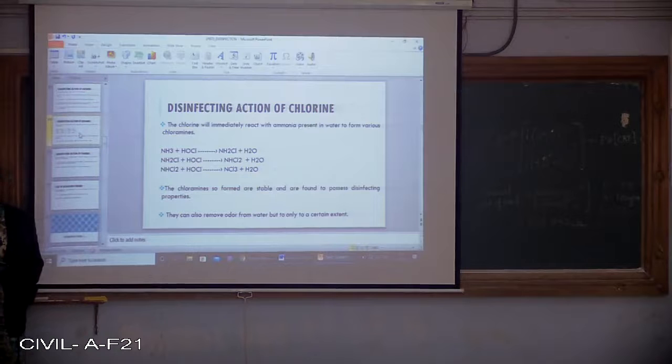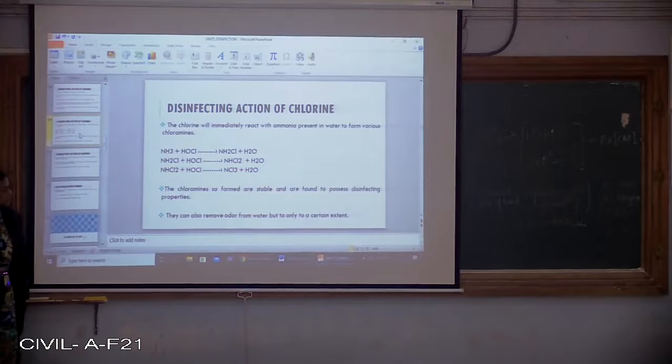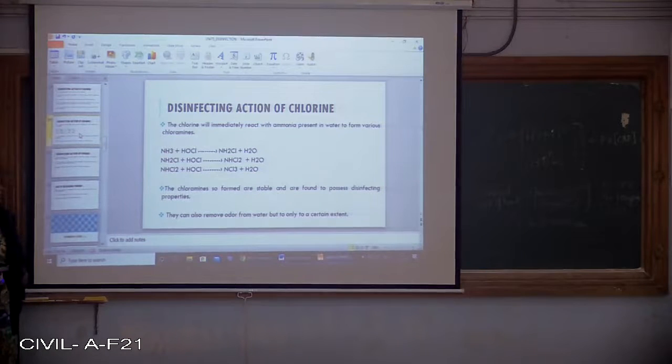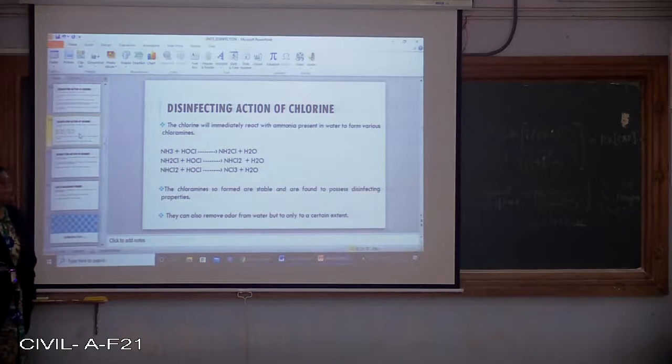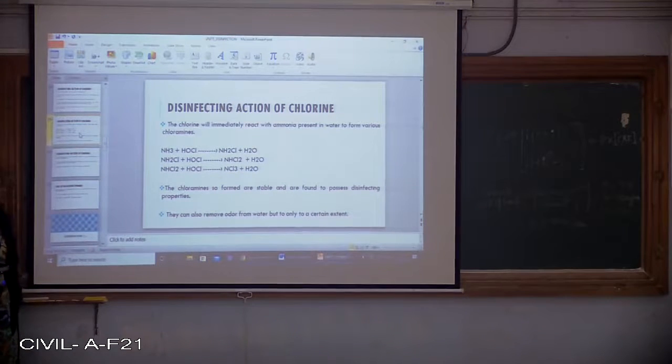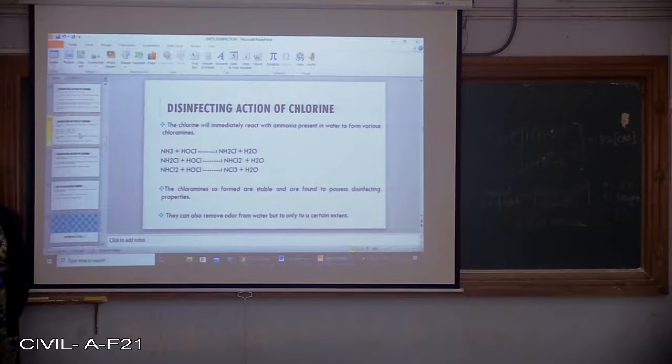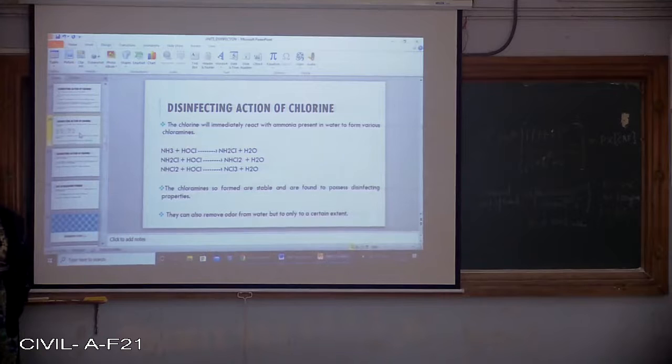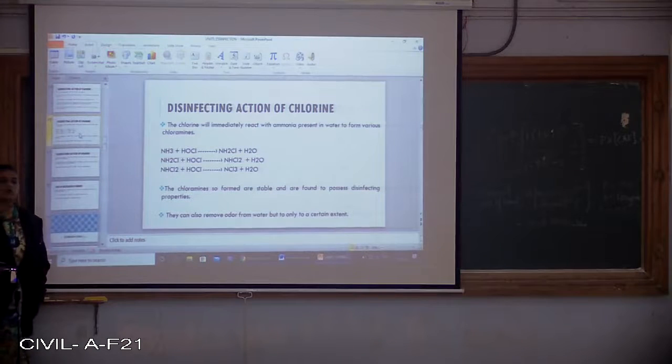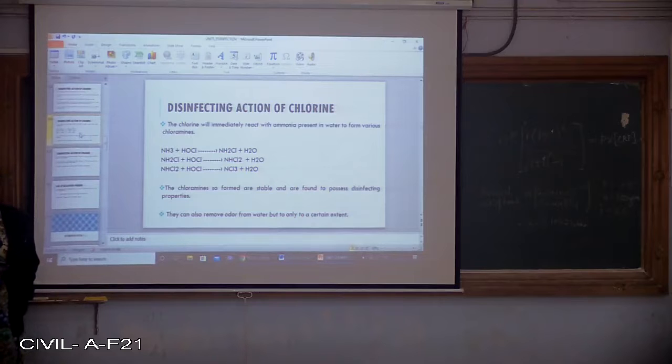NH3 plus HOCl will give you NH2Cl plus H2O. NH2Cl plus HOCl will give you NHCl2 plus H2O. NHCl2 plus HOCl will give you NCl3 plus H2O. So these are the three reactions we see whenever chlorine comes in contact with ammonia present in water.